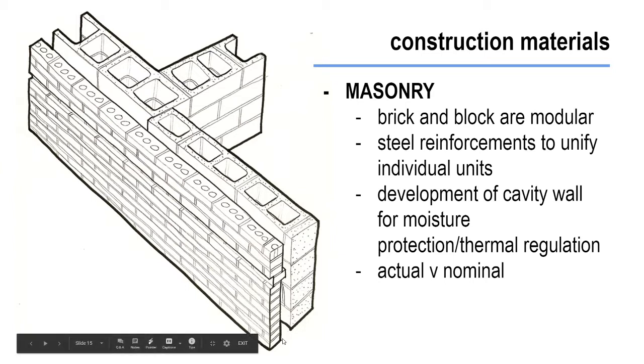And so we can see that there is an empty space between these bricks and these CMUs. And that's just to allow for, as water seeps into these bricks and goes through, it'll just kind of come out this other side, and then it'll get kind of transferred towards what are called weep holes, and it'll just kind of come out at the very bottom.